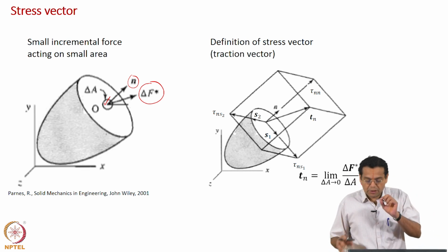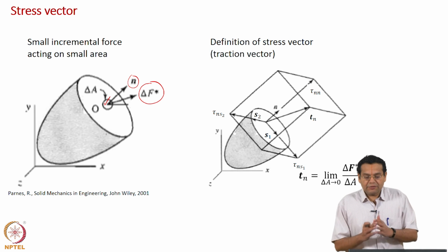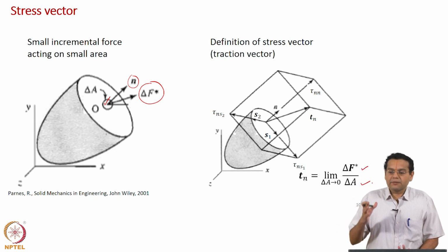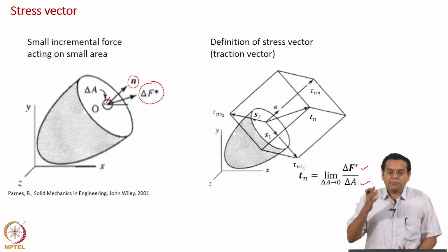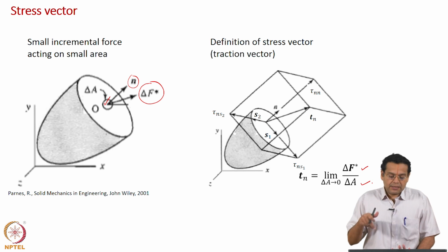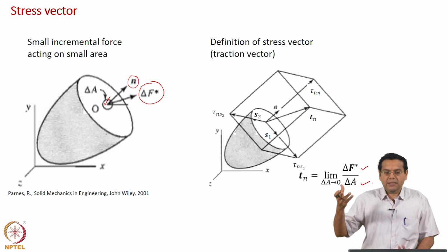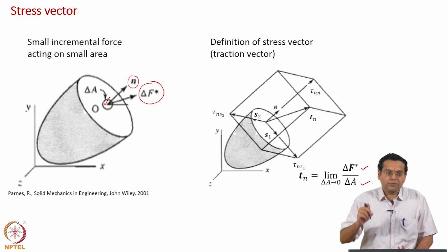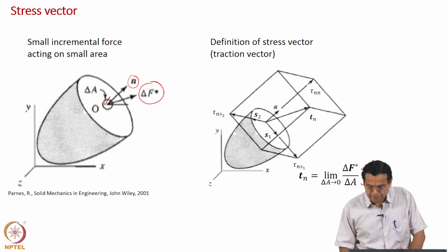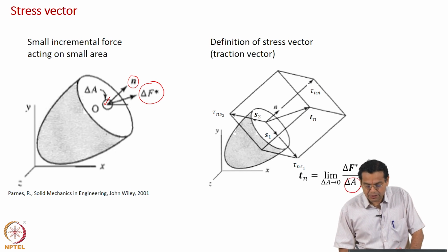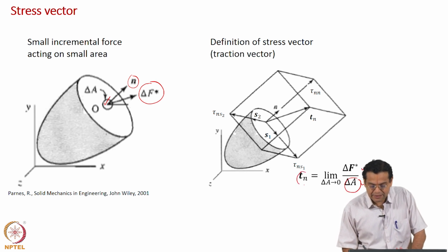The physical significance is exactly as we did earlier, writing the balance for a small volume and then shrinking the volume to a point, so that you get the differential form. Remember, all the terms in our equation should be point values. We are going to go back to the fluid mechanics linear momentum balance equation in differential form. On the right hand side, the point value of the surface force means that my definition should be valid at a point. That is why I make delta A tend to 0, so that I get the stress vector.